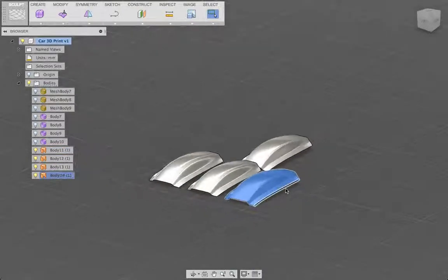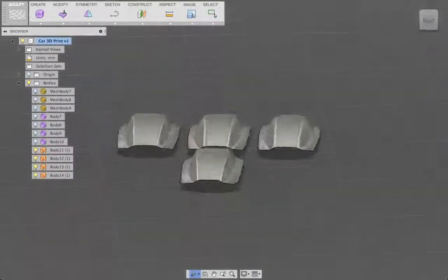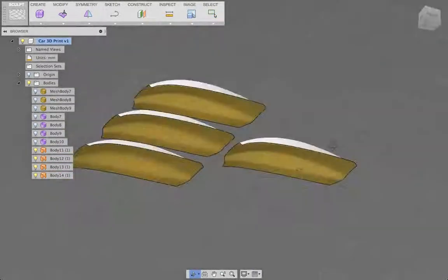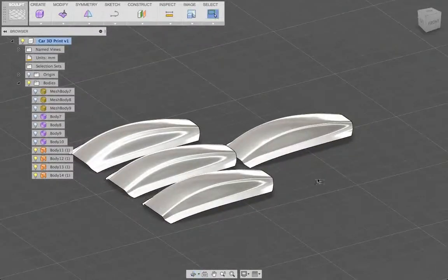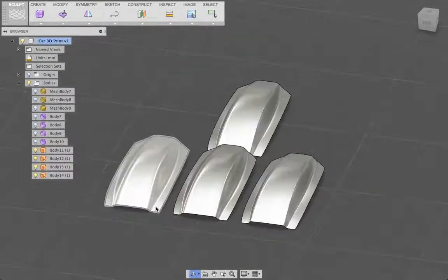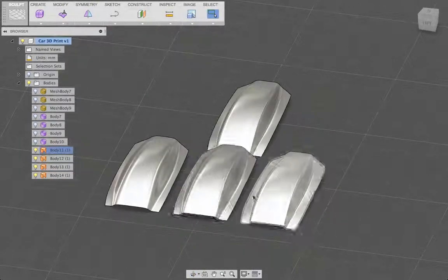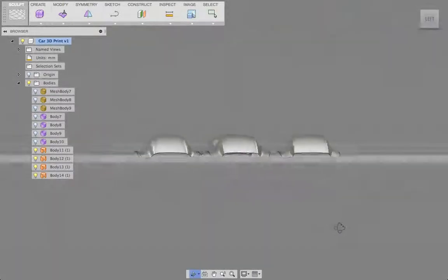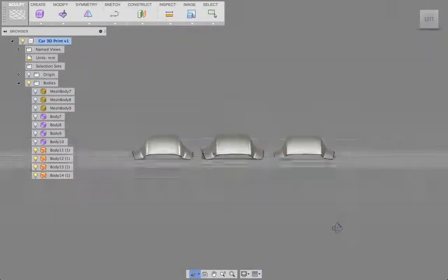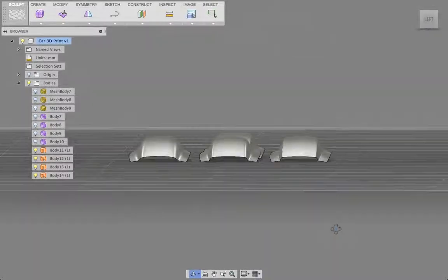Oh, okay. Well, but you notice those are now my B-reps. Those are all one surface, so of course that's the reason why you don't see any lines on it. But you see that the conversion into a NURB surface was not really a problem as well. Even the NURB surface perfectly matches the T-spline object.